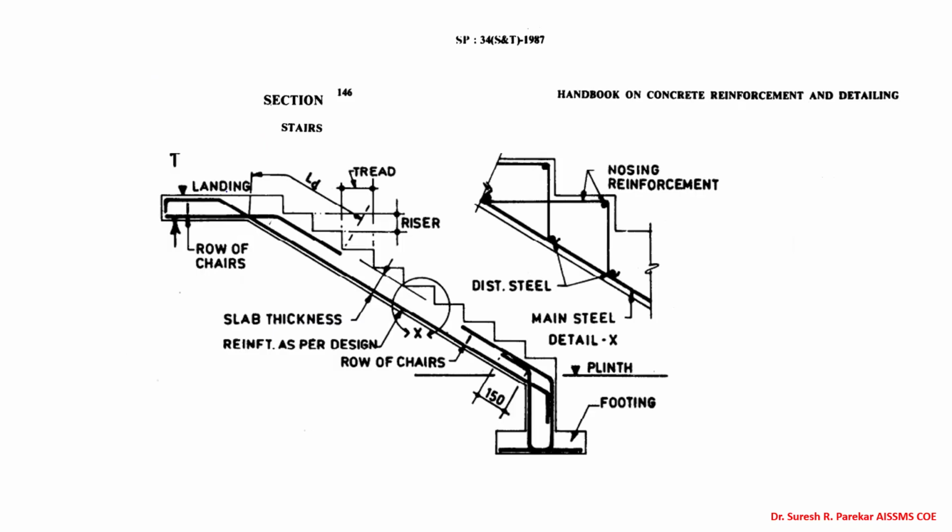So this is staircase. Now I already mentioned, you can see this bar is not coming down, this bar is going up. Why is it going up? When we make it straight, then we have sufficient concrete below it, and concrete will not crack. If I take this in this fashion, then what will happen? We have concrete over here.